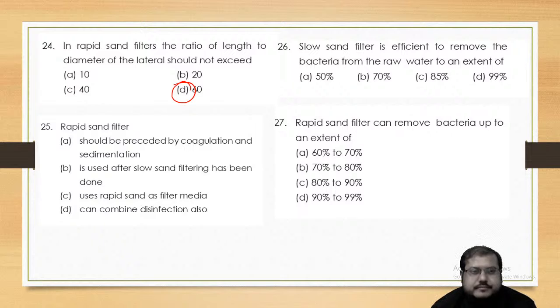Rapid sand filter should be preceded by coagulation and sedimentation. Is used after slow sand filtration has been done. Uses rapid sand as filter media, can combine disinfection also. So question number 25A.